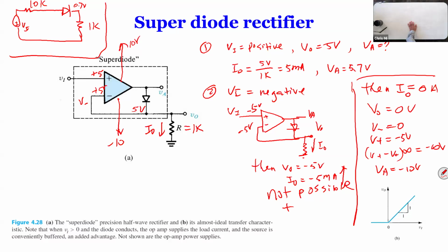So when it's positive, what happens? The voltage is going to cross the diode and then supply both resistances. If your input is 5 volts, how much voltage do you get at the output? Like 0.45 volts. Not 5 volts. It's very small, less than 10%. So a significant voltage is dropped inside the internal resistance.